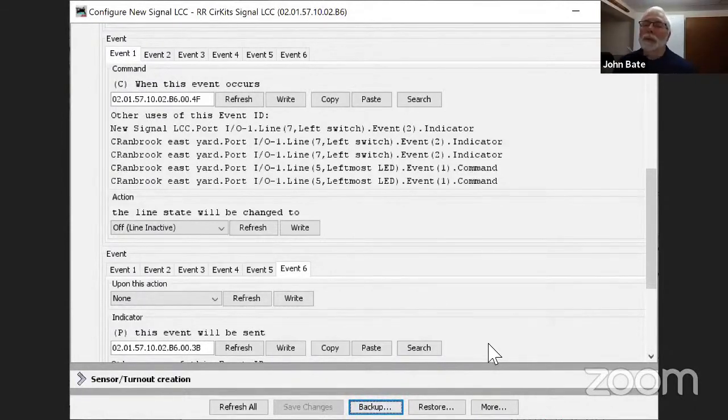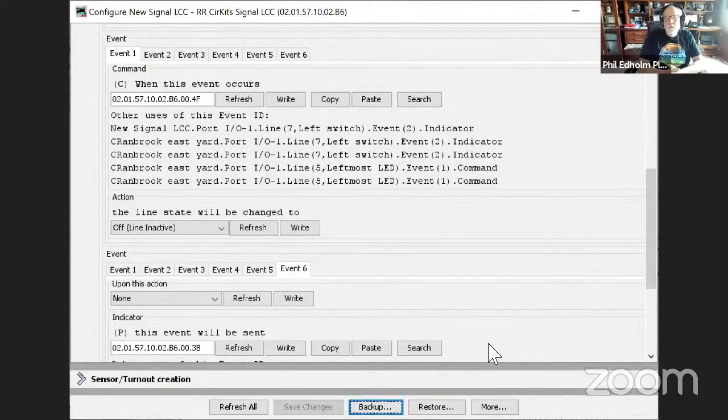But they're shorter. Exactly. So my whole point is, the reason you locate the nodes out is because the wiring is a mess. But where you put the nodes, you put a Cat5 cable and you run it back 30 feet, 20 feet, and then you plug it in. There are these 48-port patch panels where you can plug 48 Cat5s in the front, and in the back you get punch downs, and you can punch those down over into the Arduino. You've now concentrated the Arduino in one place.